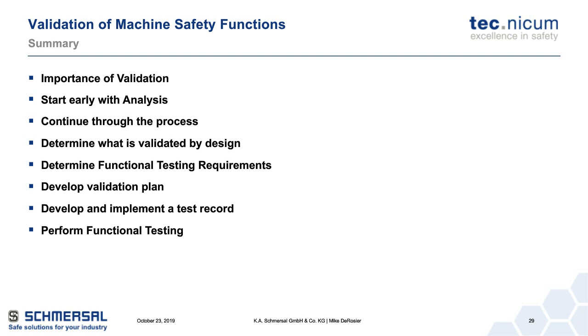It doesn't stop there. Now, what you see with validation, and specifically in ISO 13849, they call out that validation should be performed by somebody independent of the design. But they do take a specific note. It doesn't mean you need a third-party consultant coming into your company to do that. But if John designed it, maybe Jane should be the one that looks at it and validates. They're colleagues, they work together, but somebody different than the design so they can look over everything and prove it out. It's a good practice to get into.